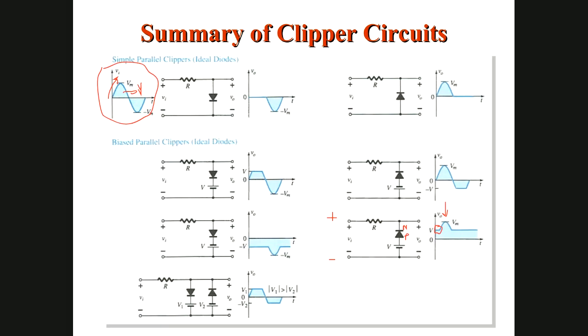but if you talk about the negative half, in case of negative half, it is negative, it is positive. Now both of these signals, whether it is input signal or this battery, are making a diode forward bias, so it will be like a short. If it is short, your output is parallel to battery. If it is V, your output will also be V. So this is how you will get it. So I think it is clear. Do you have any questions? That is all about Clipper.